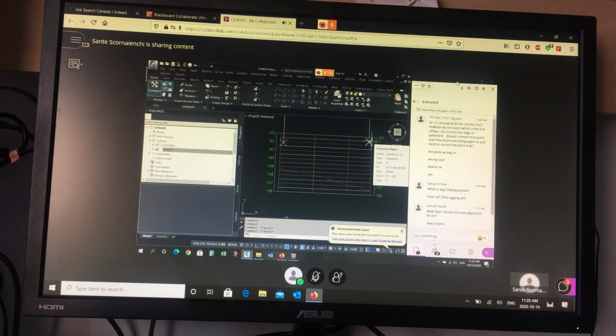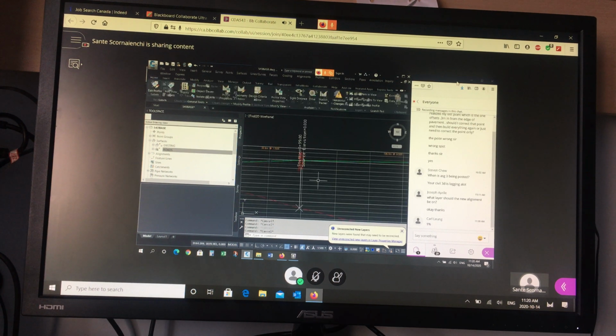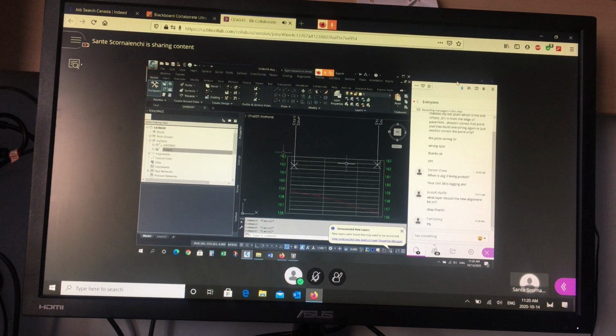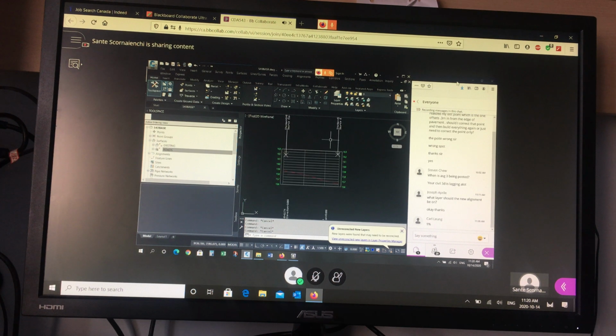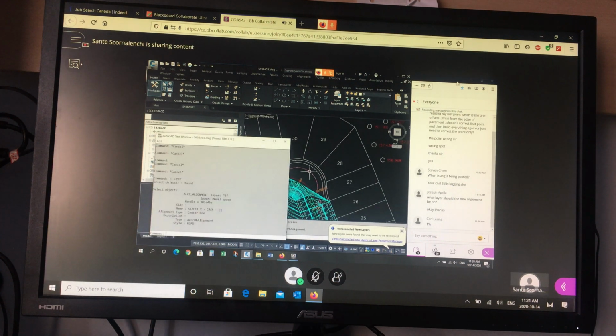Remember when we designed our center line? Exactly. So this gutter, remember this green thing? I want to create a layout profile right here by connecting those 2 dots. So here's what I'm going to do. I don't like to type, so I'm going to list the alignment name. So there's the name of the alignment, the center line alignment of the gutter.